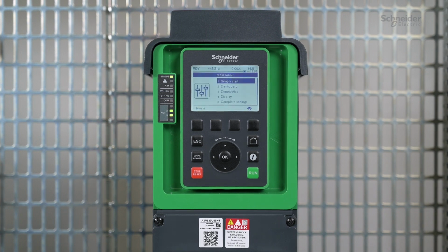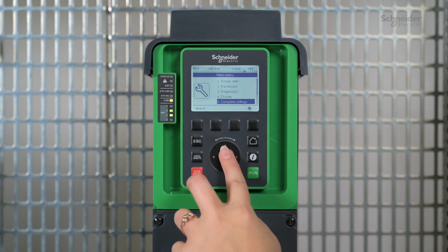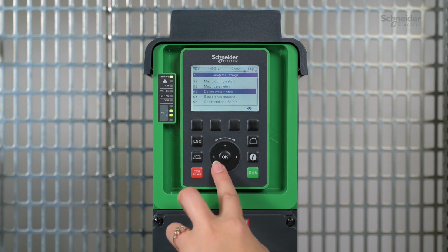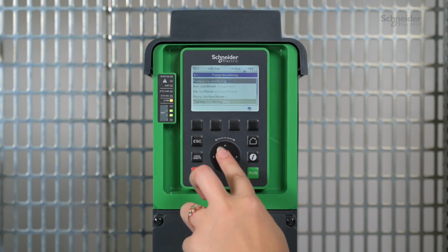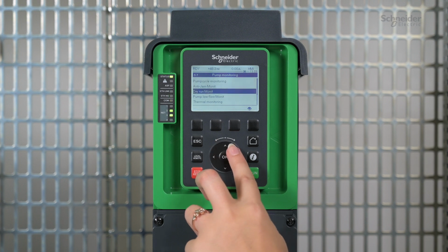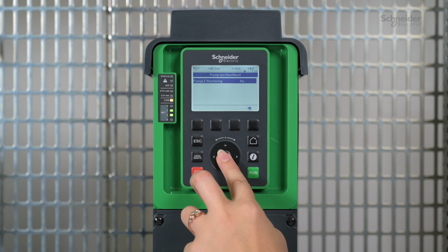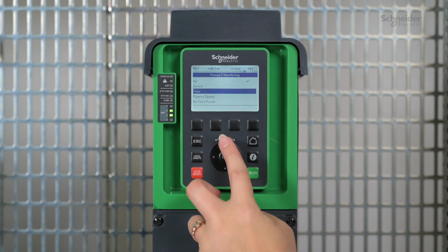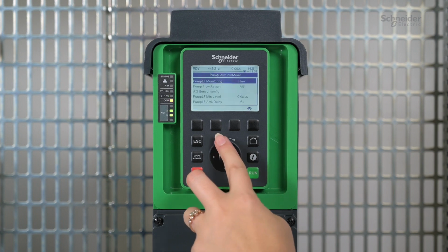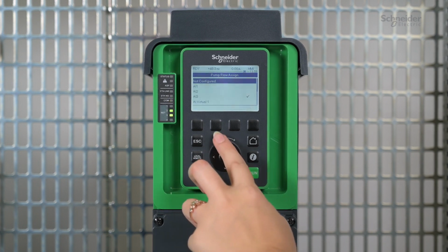The estimation flow may be used to monitor high flow or low flow without additional flow sensors. Select Pump Monitoring, then Pump Low Flow Monitor. Enable the low flow monitoring by setting Pump LF Monitoring to Flow. In Pump Flow Assign, set Est Pump Flow.